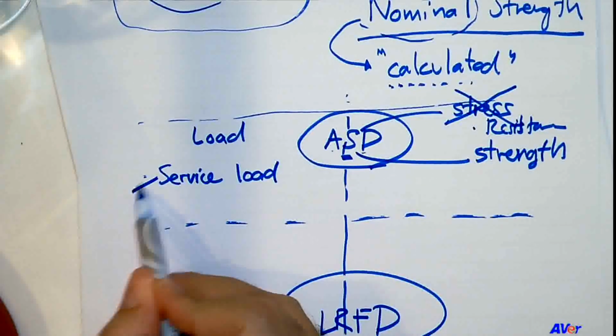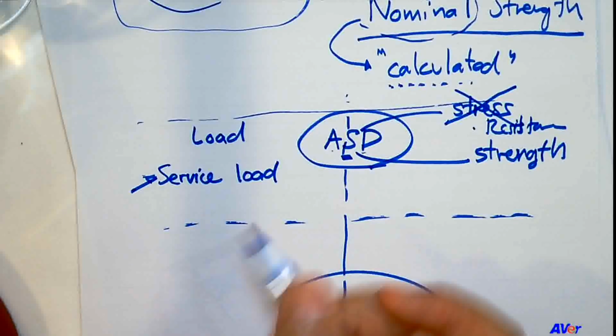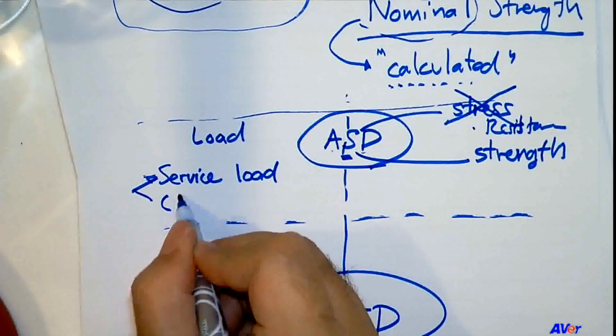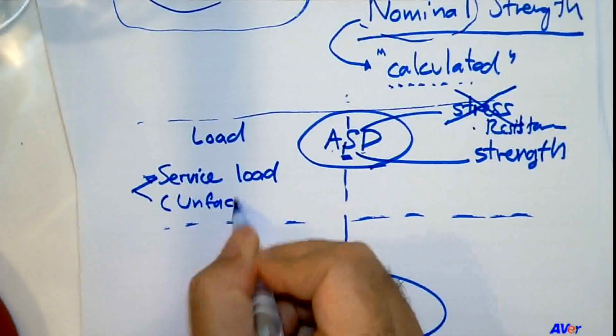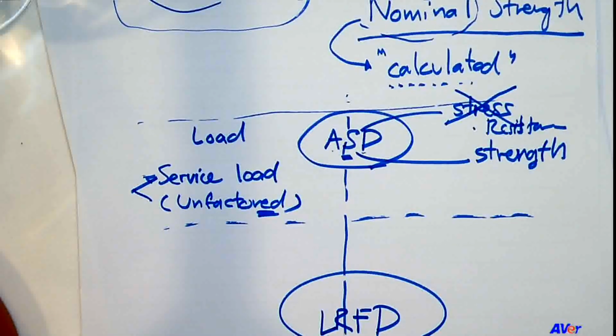The service load means that you just take the load as it is without increasing it by using any factor. So the service load, another name is unfactored load. We don't multiply the load with anything.